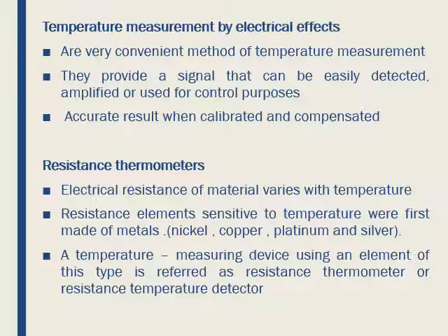Generally, thermometers are commonly used in two types for calibration purposes: total immersion and partial immersion. Total immersion thermometers are calibrated to read correctly when the liquid column is completely immersed in the measured fluid. Since this may obscure the reading, a small portion of the column may be allowed to protrude with little error.